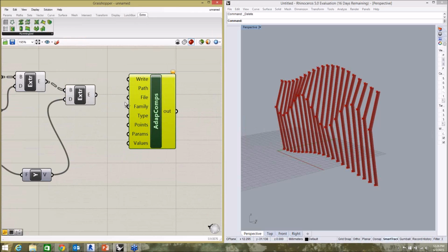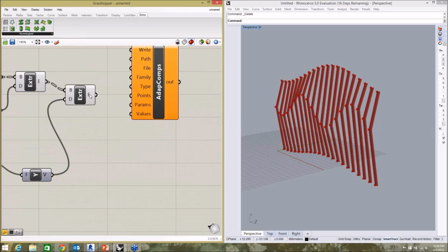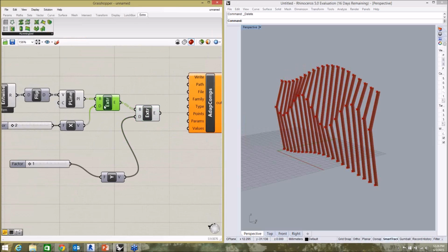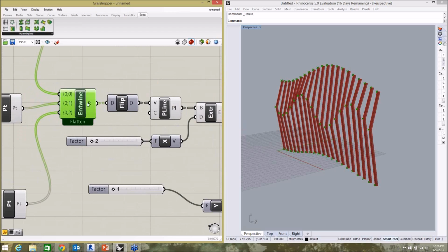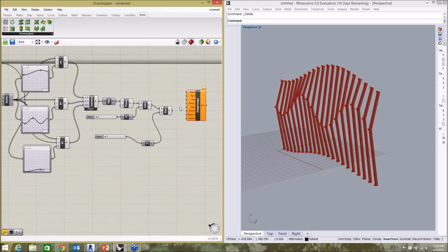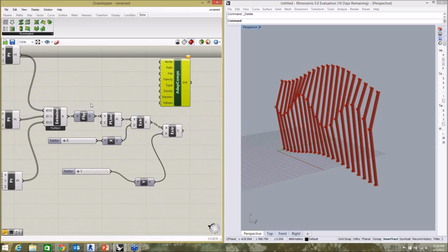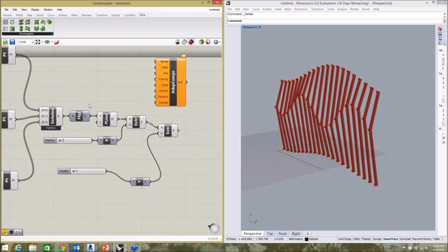All right, so it's asking me, where are the points at? Well, it's not this extrusion. It's going to be these points back here. And I'll show you, you can see as I click, you see the points highlight. These are the important points to push through. So I'm going to grab these points from here, and I'm going to put them into the points component. This node right here is what takes the information from Grasshopper and creates that CSV file we were talking about earlier, so you can access it with Revit.